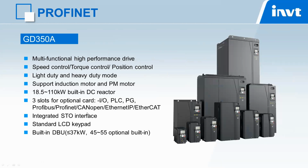The drive is the GD350A. GD350 is an IMVT, a multi-functional high-performance inverter. It supports speed control, torque control, and position control. It also has two modes: light duty, P mode, and heavy duty, G mode. It supports induction motors and permanent magnet motors. The power rating is from 18.5 to 110 kilowatts, with a built-in DC reactor. It can improve the input power factor.